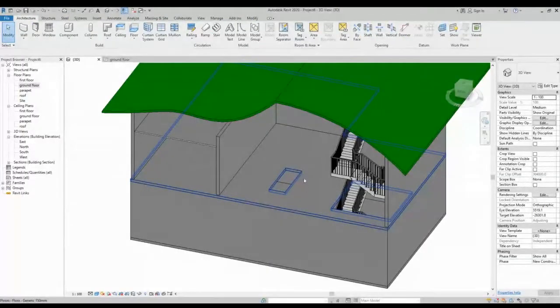They will not be sloped depending on the face that you have. So this is basically the difference between by face and vertical. Vertical is just going up, so the vertical edges will be 90 degrees. They will not have any slopes. But by face will give you this if your face is not a straight face, similar to this one.